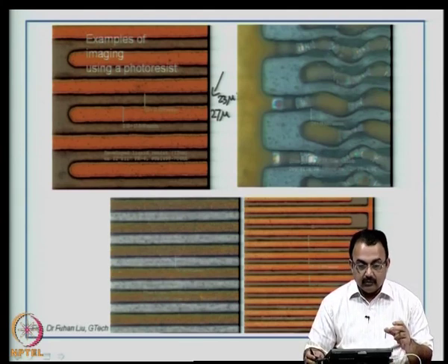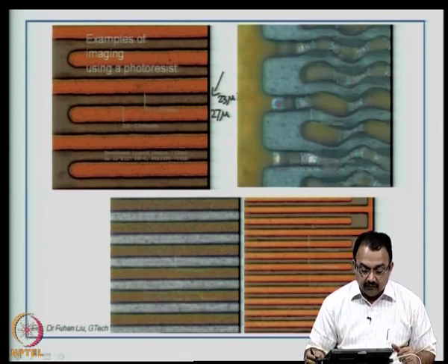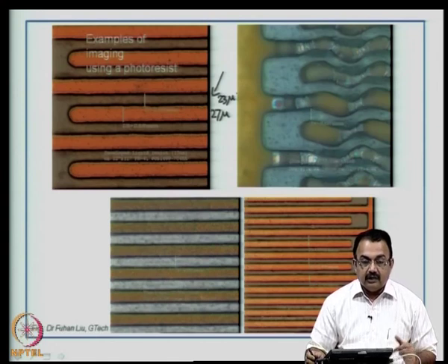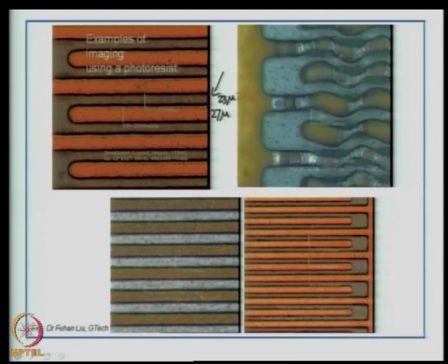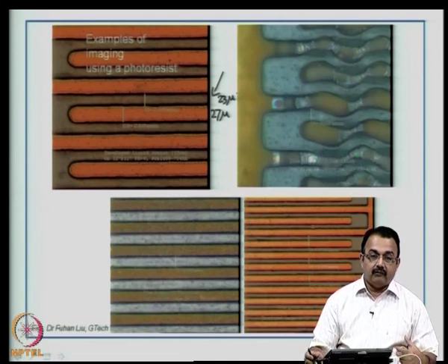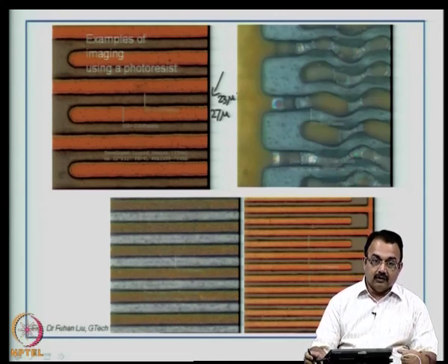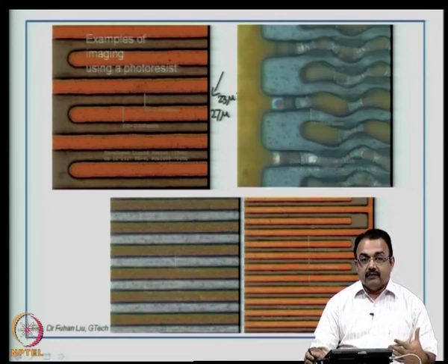Okay. This is a zoomed up image of a photoresist imaging process completed with a series of tracks, copper tracks need to be defined on the board, and you can see that the gap is 23 micron and the track is around 28 micron. So, this kind of resolution is required or expected from the photoresist material. Not all materials will afford this.